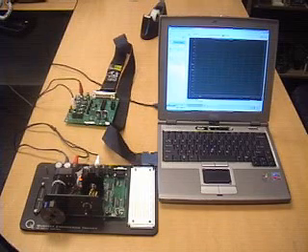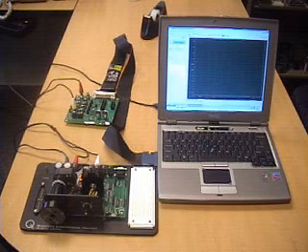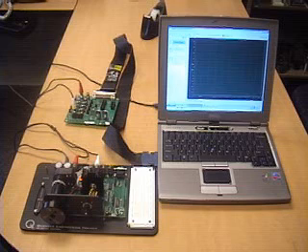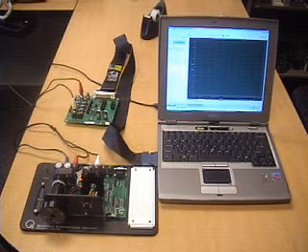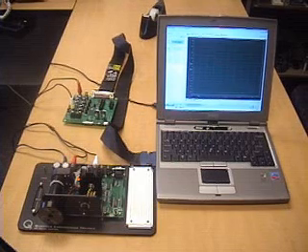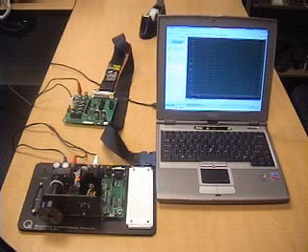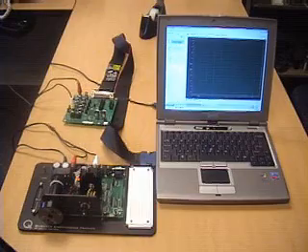So in this case, we're going to do that experimentally. And so the setup here is I have my software ready to run, and essentially the software is going to send an analog output voltage to the DC motor, which will be a square wave, so essentially a step response, and then we'll read back the tachometer signal to get the response of the DC motor from that. And then from the stimulus and response data that we have received through our software, we can actually get a transfer function for the DC motor.